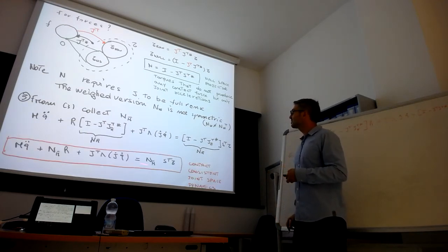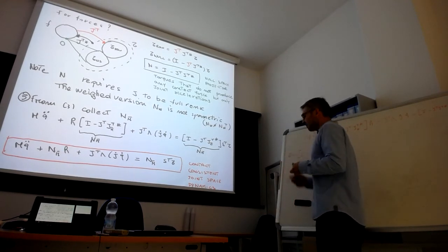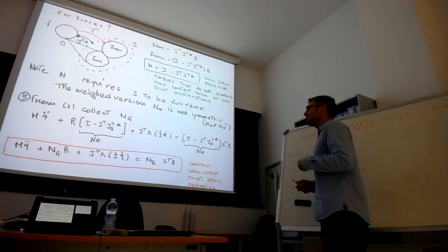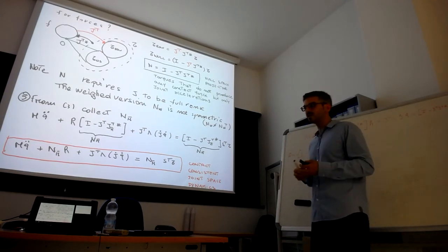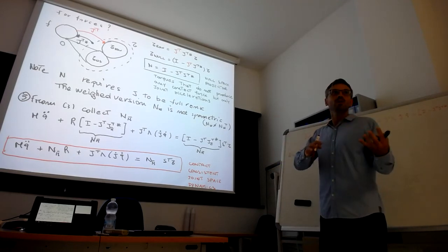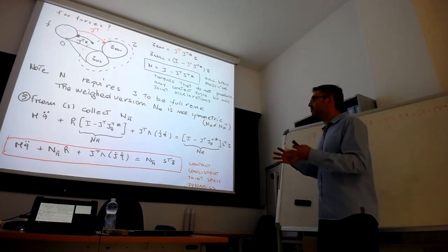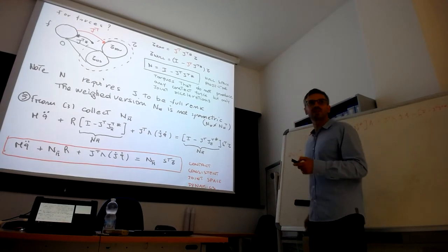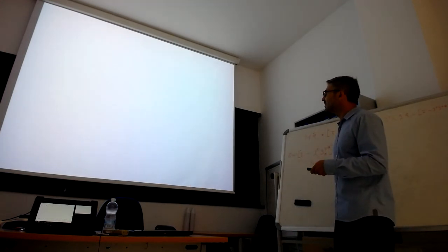Then we can write this dynamics. That is the dynamics written in a space that is contact consistent. So imagine that you have n plus 6 dynamics, and this dynamics is the projection of the full dynamics in a reduced manifold wherever the constraints are satisfied.